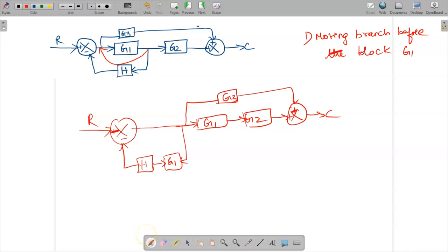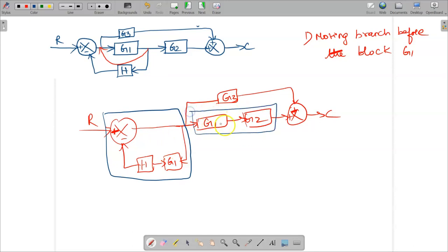So when you see the block diagram, this particular thing you can consider as the feedback path, which you can eliminate, and also these two terms are in series, which you can combine. So that is your next step: we are going to eliminate the negative feedback loop.